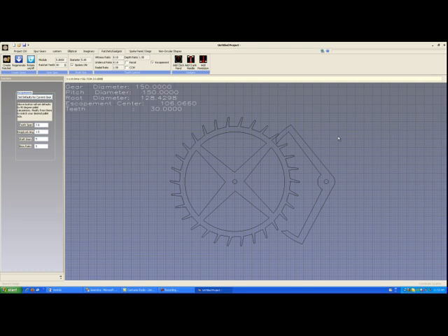The gear in the center of the screen is called a deadbeat gear, this big round wheel, and it's got teeth on it that look like pins at an angle. A deadbeat gear is called deadbeat because it beats time, and the dead portion refers to the fact that it has no recoil. A deadbeat gear should not be pushed backwards unless you have a recoil type of escapement. The escapement that I'm offering, the Graham or English escapement, typically does not have recoil. If it does, you have a problem with its design.